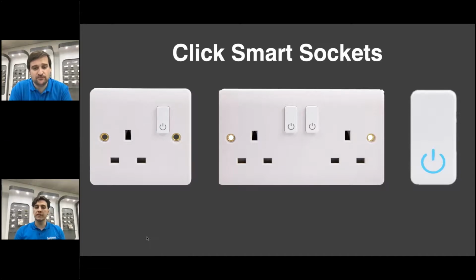So with these sockets as well, they'll fit in a standard back box, so there's no need to be putting in 47mm deep back boxes. Thank God. And the added benefit of these ClickSmart Plus sockets is that you can lock them as well. So as you mentioned, this assisted living, Darren, you can lock it. So if it was in sheltered accommodation, for example, when you didn't want people to turn the kettle on at night time, you do have that ability to lock that as well, and you can lock either side on a twin or again for a single. So that's just one of the benefits.